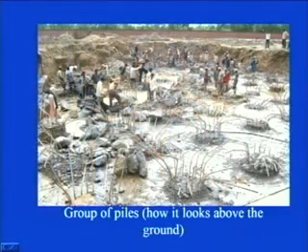You can have a look that many workers are doing their work, some are drilling. Here you see that the drilling is going on, some are just washing off that particular area. On that day it was a rainy day, so you can see some water accumulated at different places. If you have a look at this particular pile, you can see a typical lateral tie is also exposed, and these vertical bars have got bent like this in different directions.